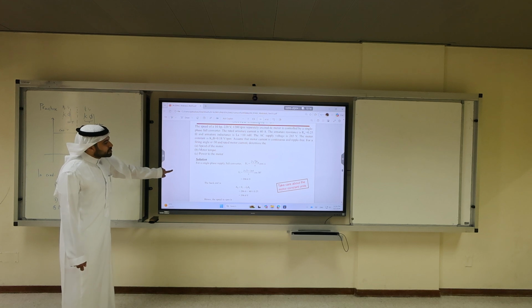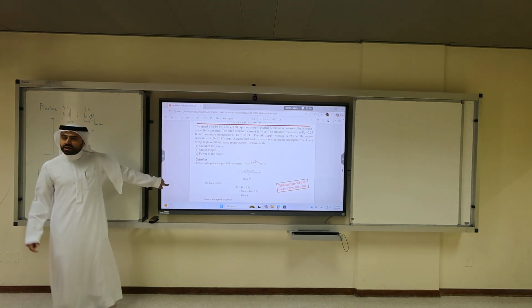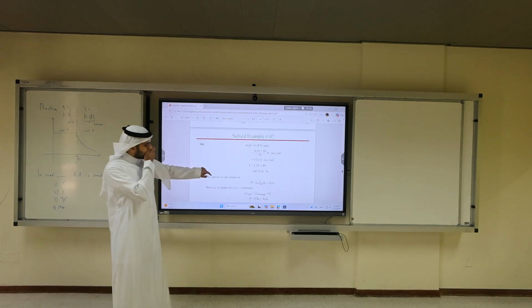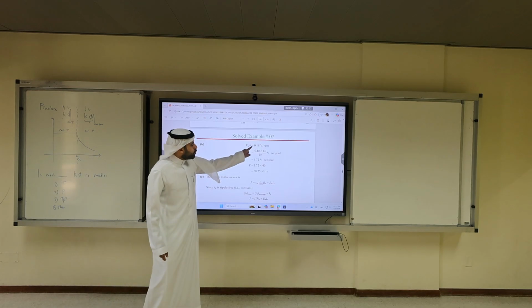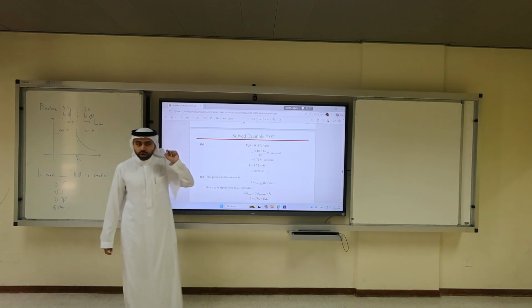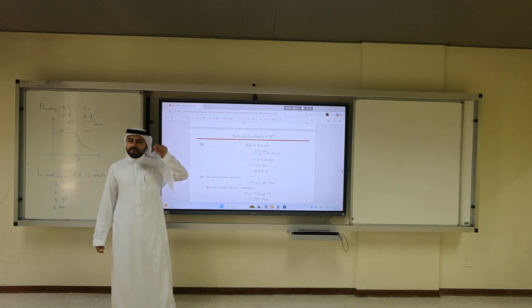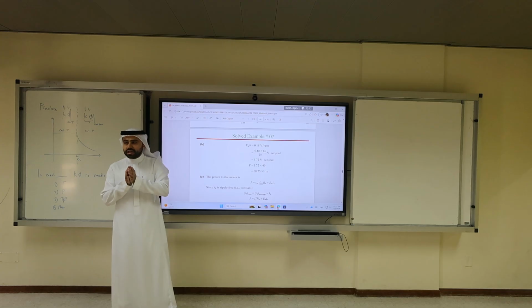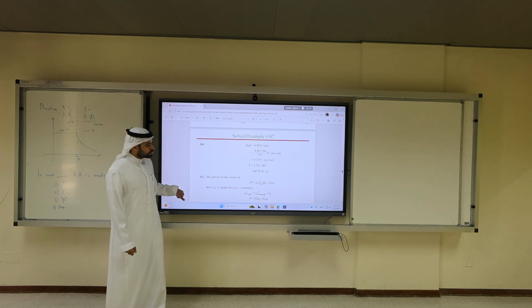Now, part B of the question, find the torque. What's the torque? It's the constant times IA. So you have to convert the constant from V over RPM to voltage seconds over radians, because the torque formula only works when the constant is in voltage times seconds over radians. And we said in class, to avoid these problems, it's better to always convert it to voltage seconds over radians.